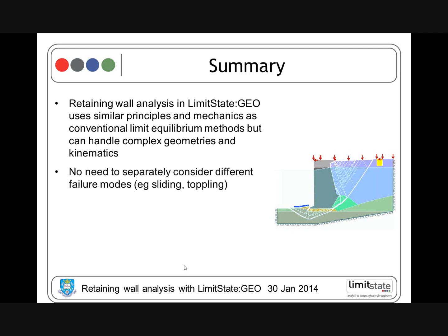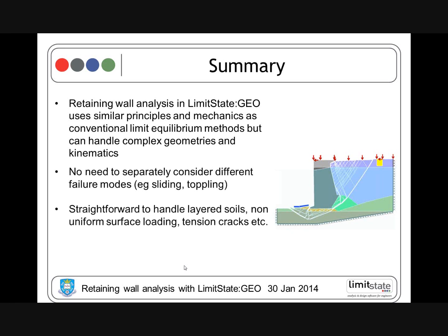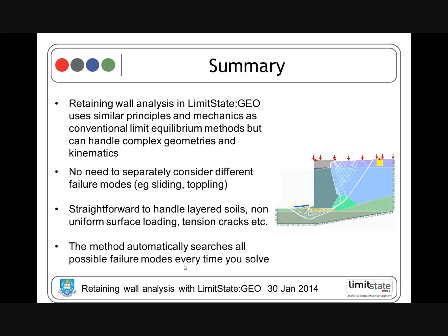We don't have to consider different failure modes. The software will automatically pick out the critical mechanism. It's very straightforward to handle layered soils, non-uniform surface loading, tension cracks, etc. And as I've said, it will automatically search all the possible failure modes every time you solve.